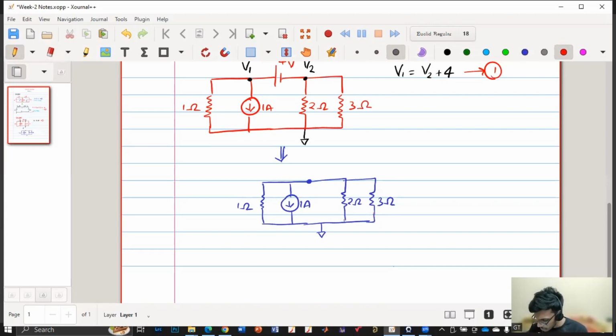Okay. And this terminal is considered to be as V1 and V2. So we need to use both the V1 and V2 when we are writing the equation. Say the current is flowing outside. So the summation of all these currents will be 0. So from KCL, we got that summation of all these currents will be 0.